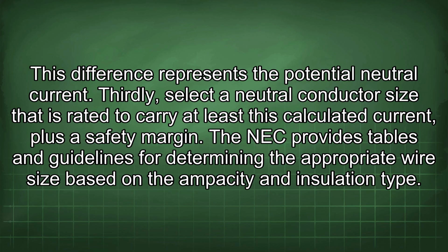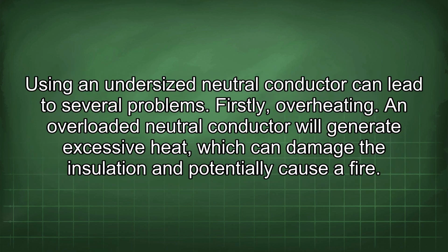Thirdly, select a neutral conductor size that is rated to carry at least this calculated current, plus a safety margin. The NEC provides tables and guidelines for determining the appropriate wire size based on the ampacity and insulation type. Using an undersized neutral conductor can lead to several problems.